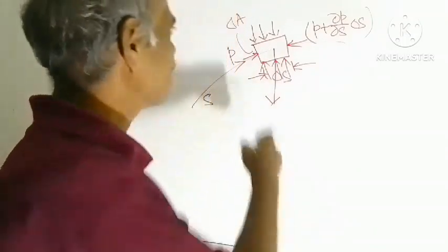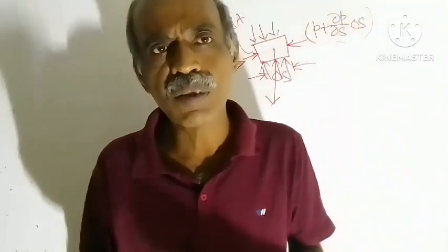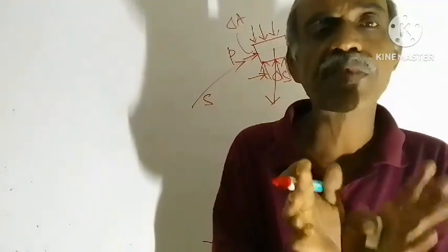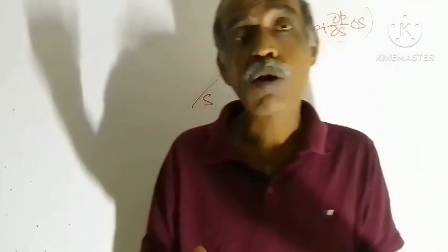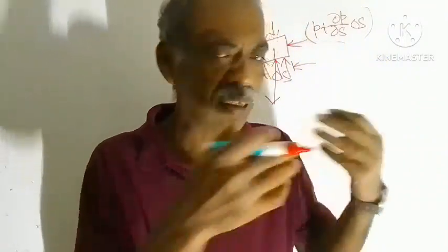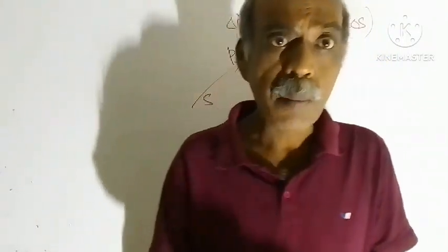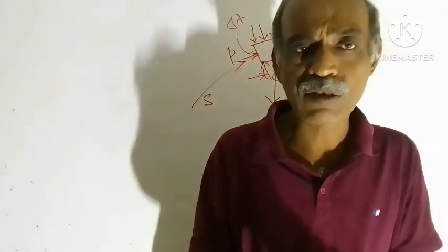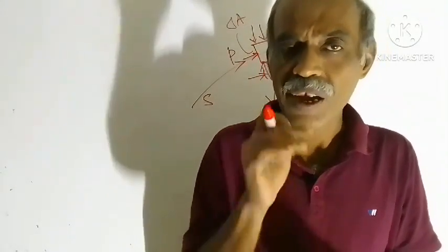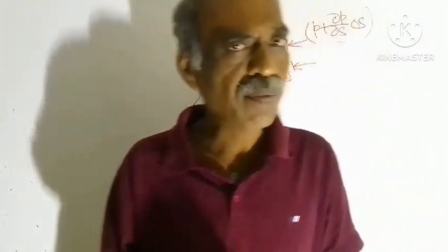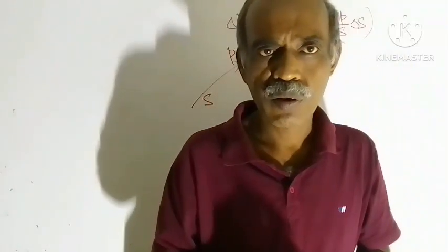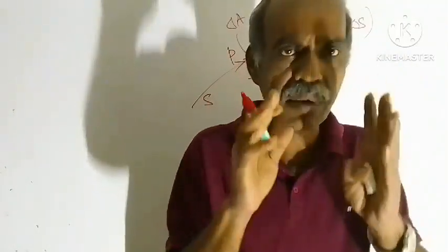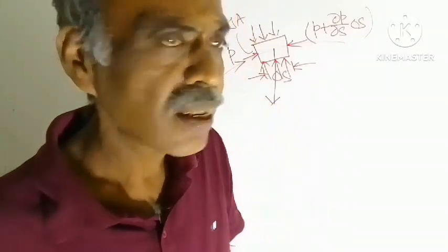One more thing, here this fluid element is very small in size. Therefore, we can assume that density within the fluid element remains same. We are not talking about constant density flow. Here in this case, density may change, but since the fluid element which has been taken is very small in size, therefore we can consider that there is average density rho. Means within the fluid element, density remains constant.